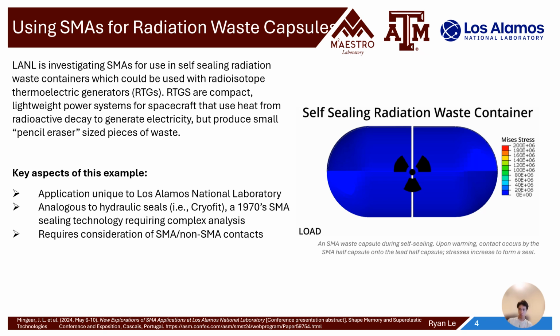So these capsules are half lead and half SMA, and the SMA half can be pre-expanded and then stored at room temperature awaiting deployment. When needed, the SMA can be placed over the lead geometry, and then the radioactive heat from the waste will actuate this shape memory, reducing the SMA diameter and then providing a semi-permanent metallic seal.